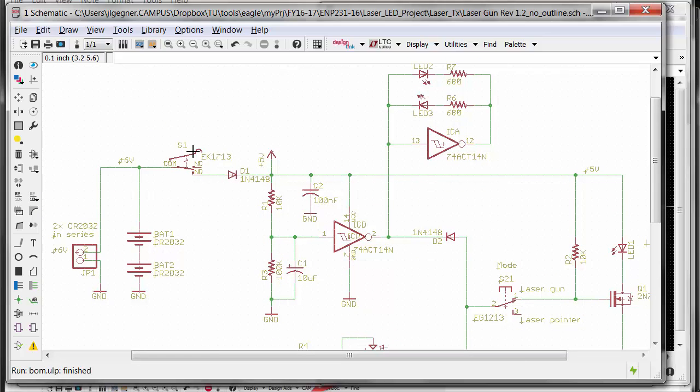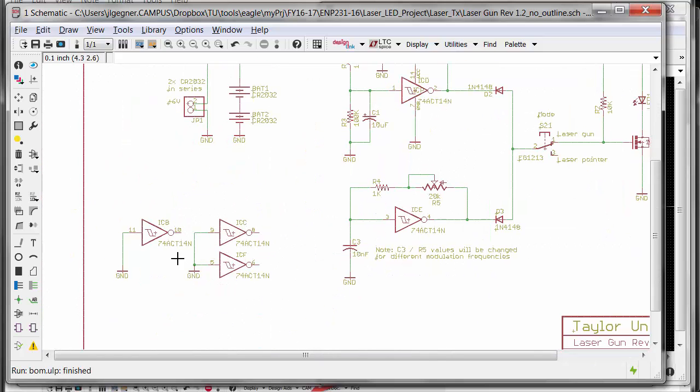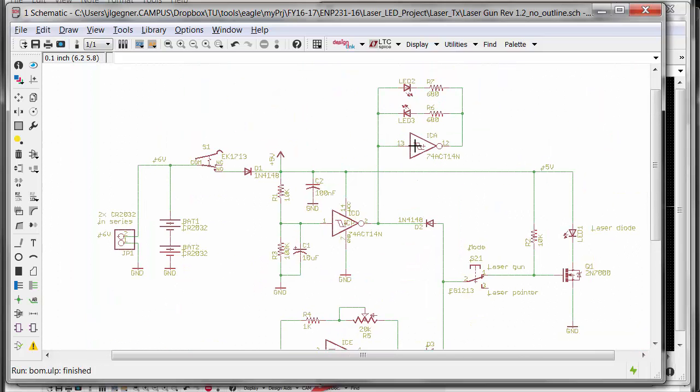I've also changed the switch from just a regular 4-post push button tactile switch to a lever switch, and I'll show you more of that in a minute, and I'll show you where you can get this part if you want to use it. And then lastly, I took one of the unused logic inverters that was sitting down here before, and I placed it up here. It's driven off of the output of this one-shot, if you will, this timeout timer.